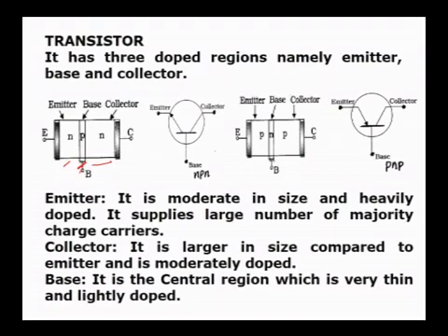And usually transistor is used for amplification purpose. And one more thing is, in case of the distinction, NPN and PNP transistors are the two junction transistors that are available. They are also called bipolar junction transistor, BJTs, and the circuit symbols you have to be careful about. Here the arrow is shown outwards, here the arrow is shown inwards in the PNP transistor. In this case, you can remember NPN transistor like arrow not pointing in, the arrow is pointing out. Basically, the arrow represents the conventional flow direction when you are using the transistor in a proper manner. And when you bias, usually emitter base junction is forward biased and collector base junction is reverse biased.